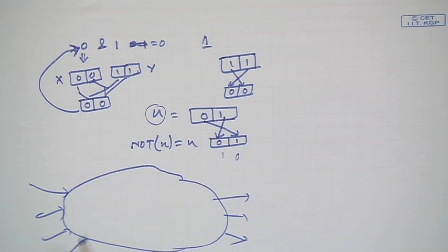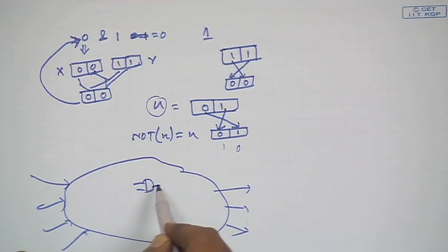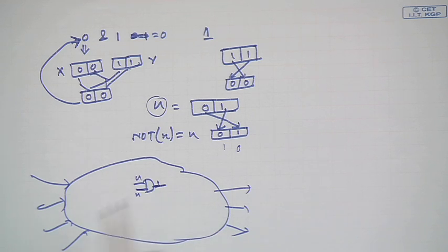Now, if I am trying to simulate this logic circuit, and all of a sudden I want to check what is the output of this AND gate, that is not possible because these values are still unknown. If I do a simulation here, I will get a 'u' at this point. So most of the values will remain as u.